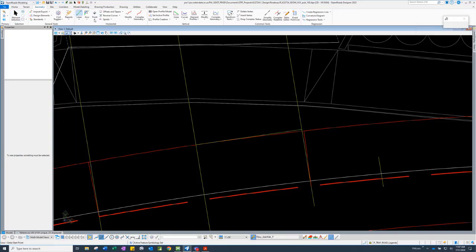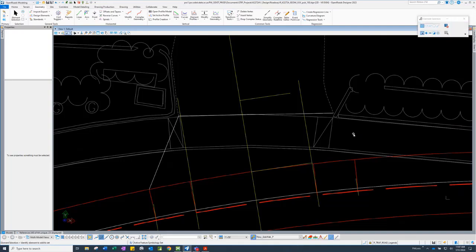So we'll do the same for this, the wing. I'd use a perpendicular snap, go to the back of sidewalk. From there, I will switch the feature definition. I'll do a match, because I need to do the asphalt. And in this case, the partial offset shows me that I'm not quite lined up with the existing. This is an existing driveway, and therefore I need to be over here.